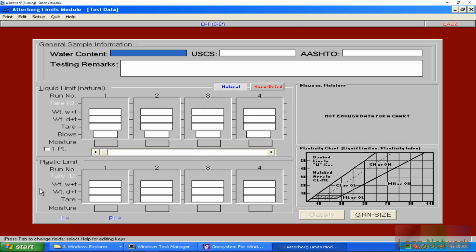Anything that is a moisture content for soils and aggregates, which aggregates is another fancy term for rock, you get your material at whatever your wet state is with the tare that you're going to use, and a tare is just a container that's going to hold your sample that is oven safe. So you get your wet sample in there, you put it in the tare, you put it in your oven. Your oven's set at a temperature, at least for right now, the specification says 230 plus or minus 9 degrees Fahrenheit, or 110 plus or minus 5 degrees Celsius for everybody else. And you let it sit in there until it stabilizes. Depending on the method, some say 12 hours, some say 15 hours. And sometimes, if you can do 2 successive weigh-ins where it doesn't change, then it's dry, is another way to do it.